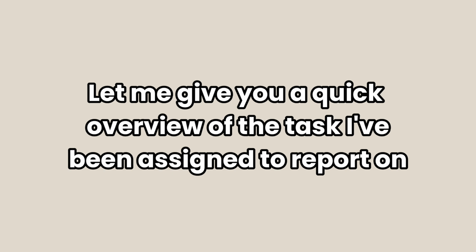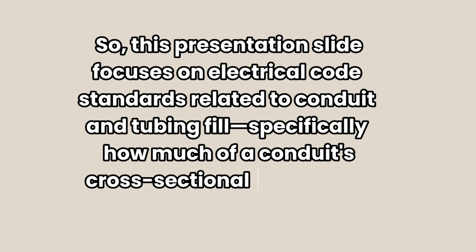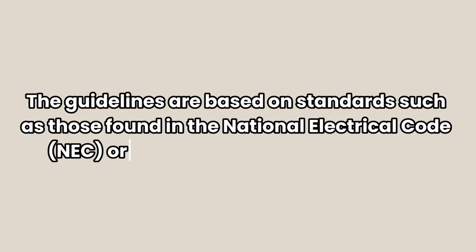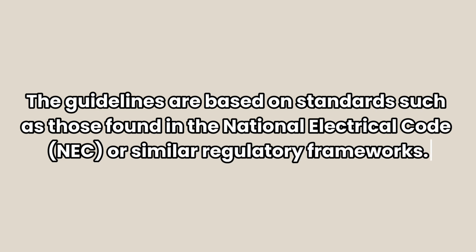Good day, everyone. To begin, let me give you a quick overview of the tasks I've been assigned to report on. So this presentation slide focuses on electrical code standards related to conduit and tubing fill, specifically how much of a conduit's cross-sectional area can be occupied by conductors. The guidelines are based on standards such as those found in the National Electrical Code or NEC or similar regulatory